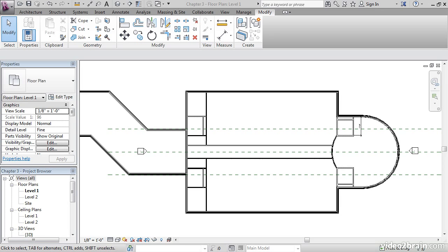In this lesson, we'll be adding a couple more corridor walls and then adding a 45-degree angle to the center of the core. Not every wall you model is going to have perfect 90-degree angles. In the middle of the corridor, we're going to add some bevels to widen the center part of the building. The objective of this exercise is to add a couple more reference planes and do some simple editing commands to create 4 45-degree corners. Open the file you've been working on or open the file called Chapter 3 and follow